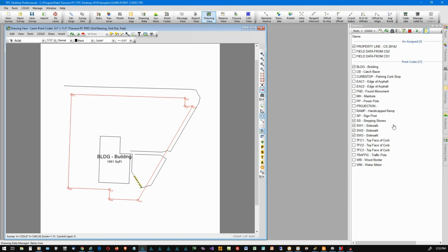So people ask me, well, when would this happen? It's not something you're going to run into regularly. One example I can give you that came from one of our users is they were out in the field one day working a long road project. They started at one end of the project one day, and then just to change things up, they went back the next day and went from the other end. So they worked from both ends to the middle. Well, dump all those points into one traverse, do a nearest neighbor sort, and you're good to go.